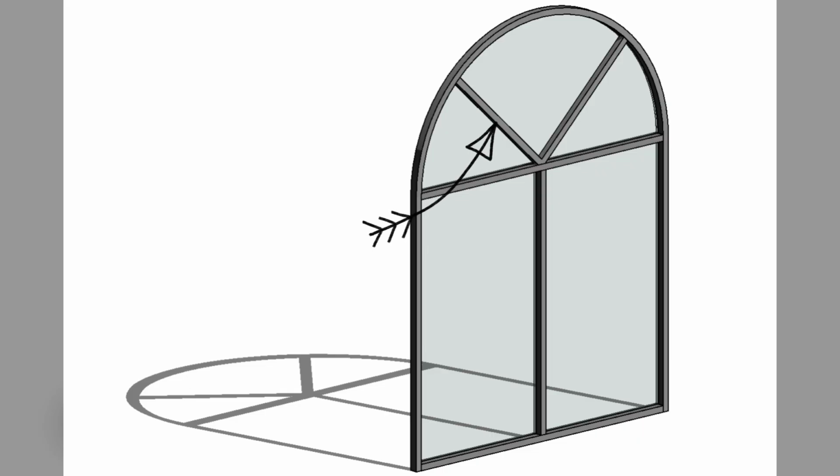So today in this video, we'll talk about curtain walls. We'll see how to add diagonal mullions in the Revit curtain wall. Usually we can add mullions in Revit in the horizontal and vertical directions only. We can't add mullions in the diagonal direction. So we'll see a step-by-step tutorial and the method to add mullions in the diagonal direction in the curtain wall.